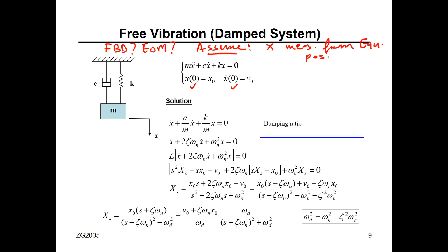So how are we going to do this? The free body diagram. We will start with the model. Start with the mass. This is my mass, and this is my displacement, similar to the model. Now show the reaction forces. We have one reaction force here from the damper, and one reaction force here from the spring. Spring force is Kx, damper force is C x dot, remember?